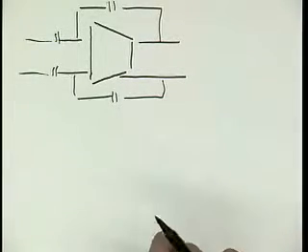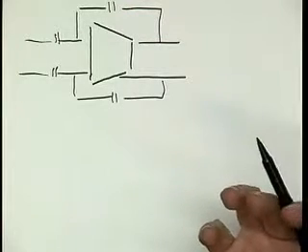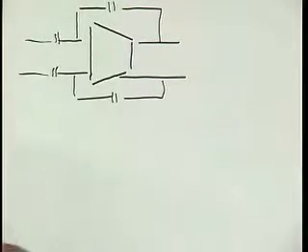Hopeless, right? But what we can do is break the differential and the common mode feedback loop individually. Now, if the circuit was perfectly symmetrical, which in SPICE it actually is, in reality not quite, but within 1%, then if we stimulate the differential feedback loop, the common mode doesn't change at all, because the gain ACDM is 0, for example.